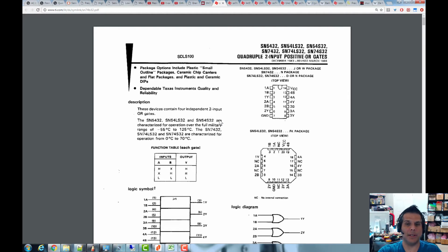And in this case, in the LS technology, the OR gate is faster. Maybe in a different technology, say LV or LVC, the AND gate is faster, right? So you would look at that. But this is a level that, if you want to get down and optimize, you need to know this math and these things so that you can do that. And again, just know that it exists, so you can say in the back of your head, I know I could make this faster, there's some law I read. You can go back and always figure it out.